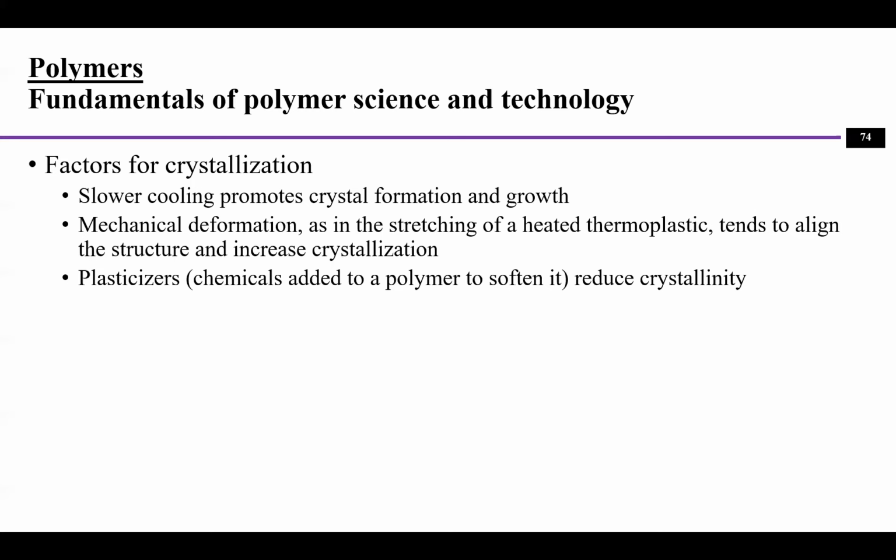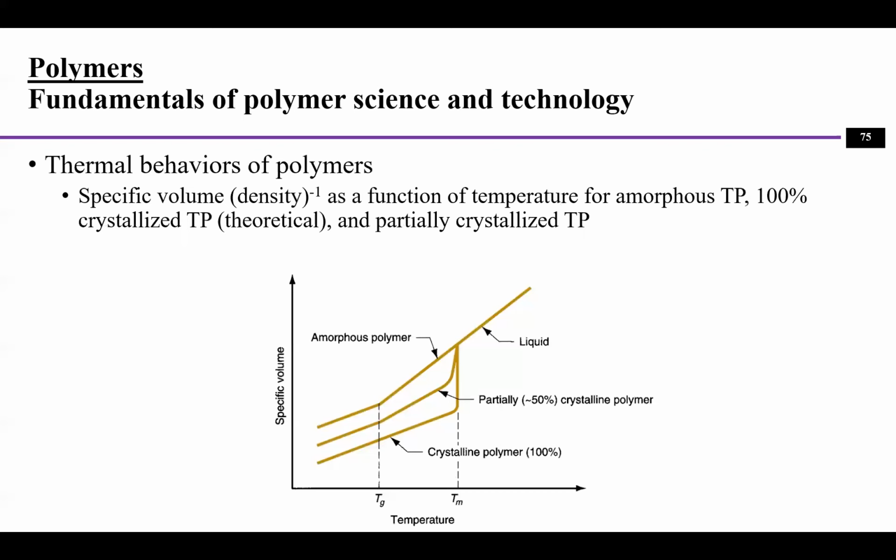And the factors for crystallization, well, slow cooling will promote crystal formation and growth, and also mechanical deformation, right? It can also tend to align the structure and increase the crystallization. Sometimes we can add some chemicals into the polymer to help reduce the crystallinity as well.